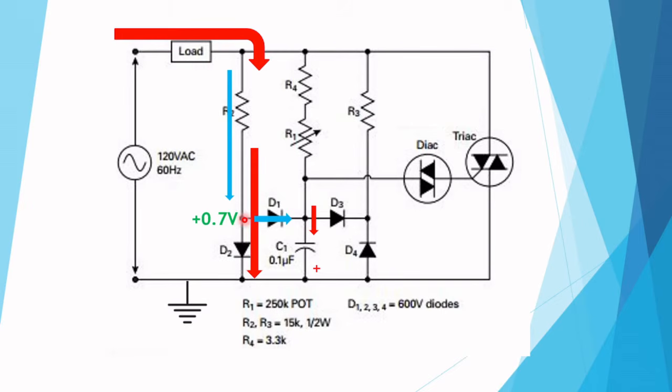As long as the capacitor has a voltage lower than 700 millivolts, current will flow through this node until the capacitor is charged to 700 millivolts. This effectively removes the negative charge present beforehand. At this stage, current continues to flow through R4 and R1, which will charge the timing capacitor, and the circuit works just as before.